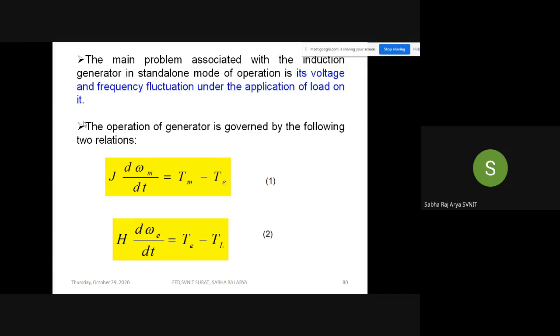In those cases, we need to maintain voltage and frequency fixed along with reactive power, harmonic compensation and unbalancing. Also, this is one case. Second case, suppose our supply side wind speed is going to vary. Then we need some energy storage element also. Whatever energy storage element we have discussed in DVR, by that one, what can we do? If we use a battery, then that system is going to compensate. That system is going to generate compensating voltage in phase with current.